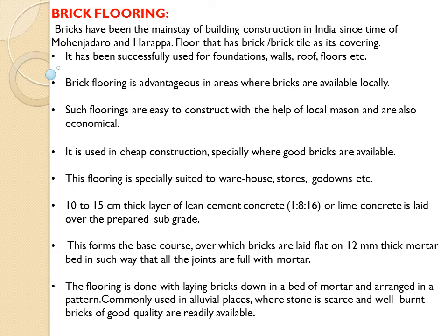Next, cheap construction. Then, using good bricks, you could make any surface very rough, right? A pattern is found, especially as very good bricks will be available. Then this flooring is specially suited to warehouses, stores, godowns. So why warehouses, stores and godowns? Because here a very heavy traffic movement happens with respect to vehicles as well as people, which requires a very strong floor.